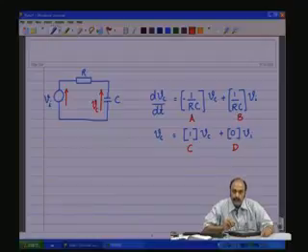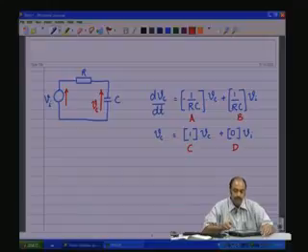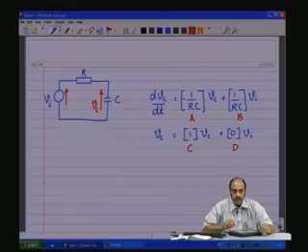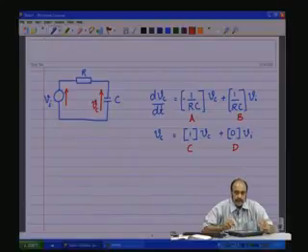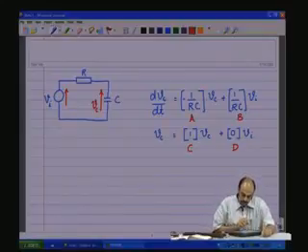These are the four matrices that you have to always feed in, whatever may be the system, because all the systems are described in the standard state space form, which is x dot is equal to Ax plus Bu, y is equal to Cx plus Du. And normally, to study the system in the time domain, the step response is a key response that gives almost all the characteristics of the system in the time domain.